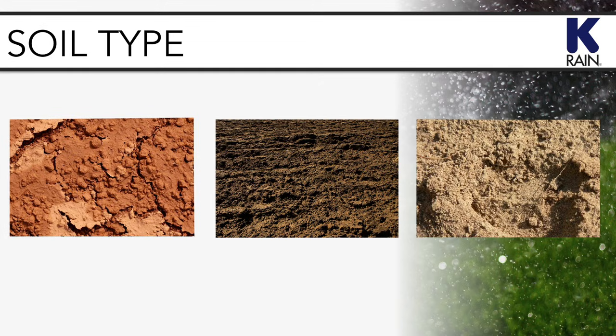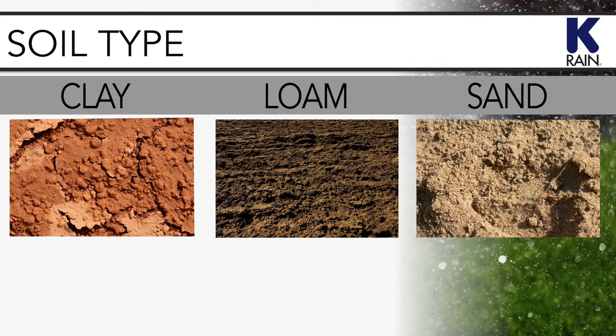You can perform a squeeze test to determine whether the soil is predominantly clay, loam, sand, or some mixture of the three. When a moist ball of soil is squeezed, clay soil will retain its shape when poked, loamy soil will break apart when poked, and sandy soil will completely fall apart before forming into a ball. A plan drawn to scale with complete and proper site information is essential for completing a design that will enable easy installation of an efficient, easy-to-maintain irrigation system.